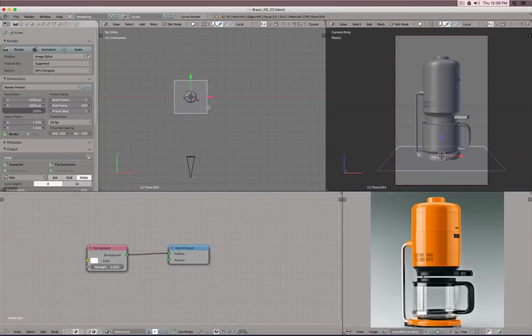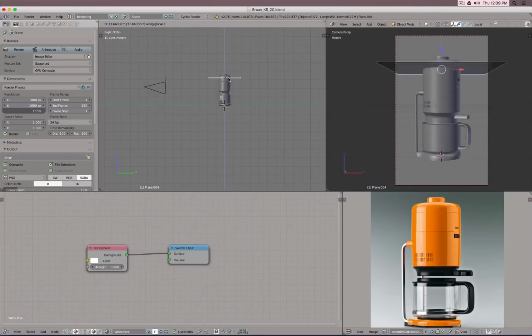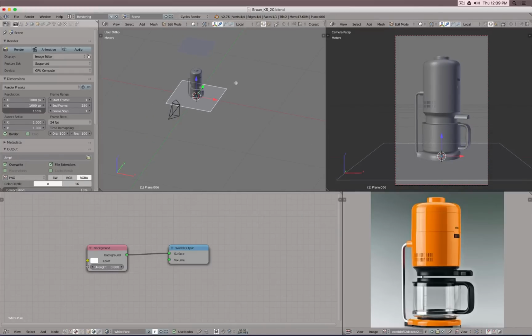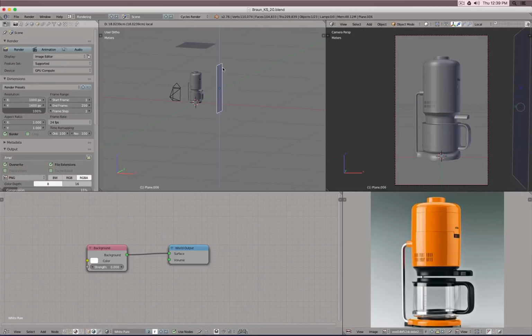We will put this one on top. This is probably just a small plane like this. I don't really know the height right now, so I will just push it somewhere to there. Another plane. This probably is a little bit stretched. RY and 90 there. Maybe move this one up. Maybe scale this down a tick. There. Okay. And Shift D, and I move it over.